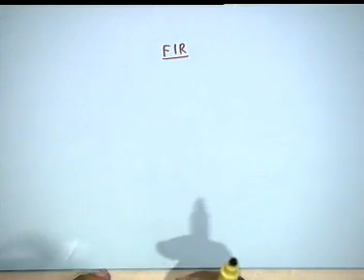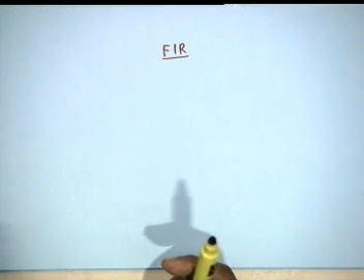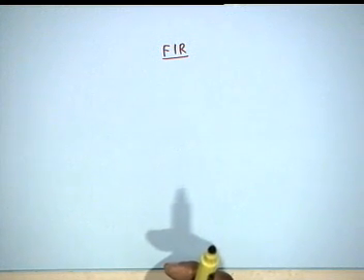This is called synthesis by analysis. Okay? For example, if you want an analog band stop filter, second order, then you know various structures that use, for example, a parallel T network. So, you draw the structure and then match the coefficients or the values of the resistors and capacitors. This is called synthesis by analysis. So, we will follow synthesis by analysis for the FIR structure.